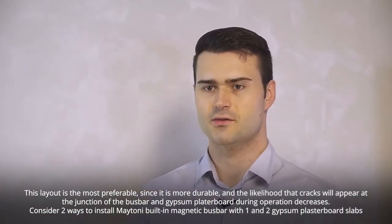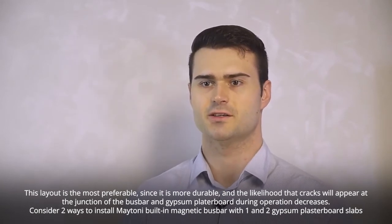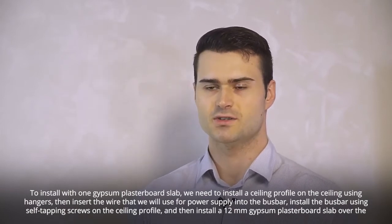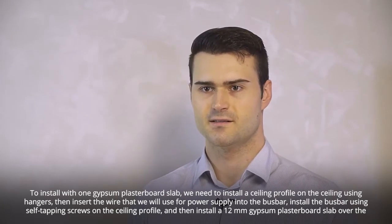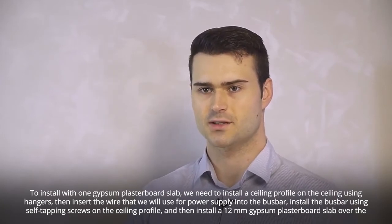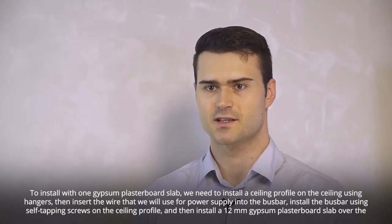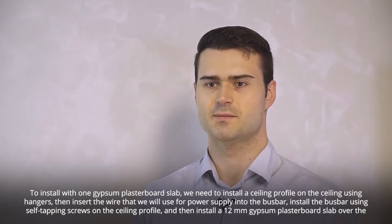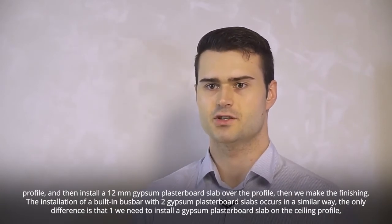Consider 2 ways to install Maytoni built-in magnetic busbar with 1 and 2 gypsum plasterboard slabs. To install with 1 gypsum plasterboard slab, we need to install a ceiling profile on the ceiling using hangers, then insert the wire that we will use for power supply into the busbar. Install the busbar using self-tapping screws on the ceiling profile, and then install a 12 mm gypsum plasterboard slab over the profile, then we make the finishing.